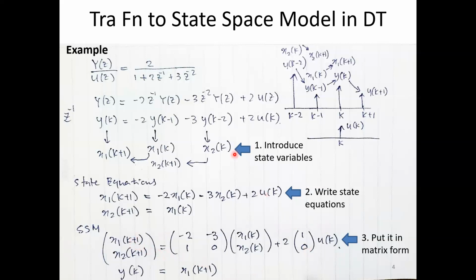When you write down a system in the form of this equation, where you can see the rate of change of state variables, and here the values of the state variables, and there's some connection matrix over here, plus some constant times input signal, right? This is what is called the control affine form of the transfer function or state space model or just model, right? Canonical form or control affine form. This is the most important form that you need to write your model in, for almost everything, analysis, controller design, etc.